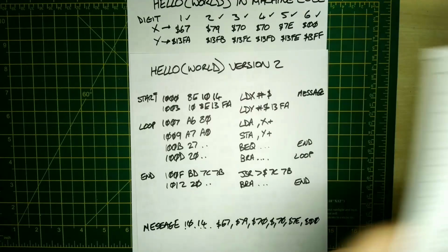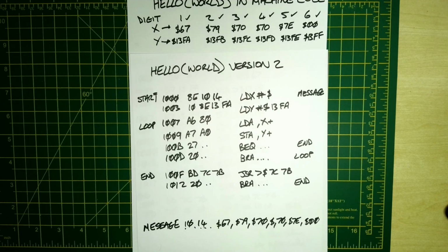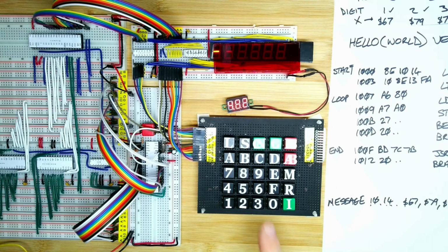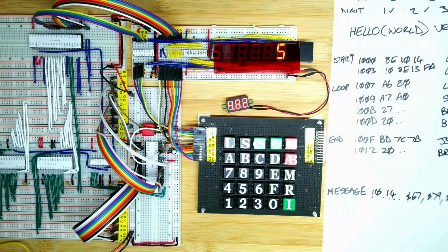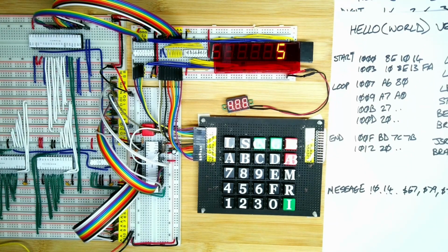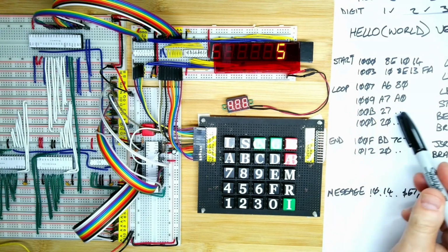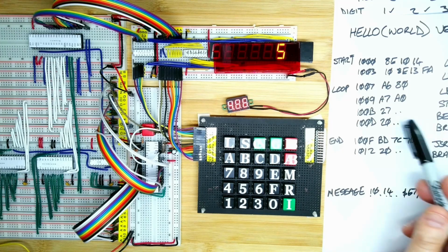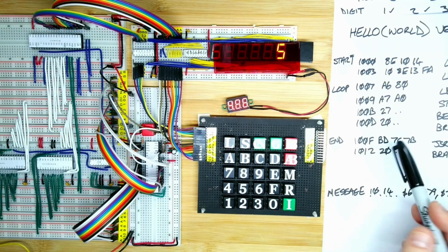So what I'm going to do is just switch the nanocomp on, and we'll run the relative offset program. Okay, so I've got the nanocomp switched on, and if you remember, we're going to run the offset program, which is at 7A00. It's going to ask us for the start address, and the first one we're going to go with is 100B, and we need to go to the end, which is 100F.